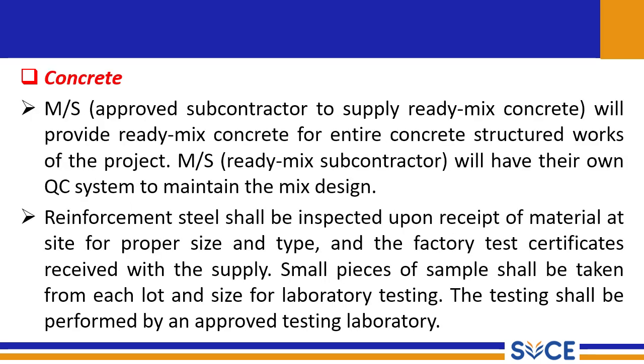Concrete: an approved subcontractor to supply ready-mix concrete will provide ready-mix concrete for the entire concrete structural works of the project, and the subcontractor will have their own QC system to maintain the mix design. Reinforcement steel shall be inspected upon receipt of material at site for proper size and type, and the factory test certificate received with the supply. A small piece of sample shall be taken from each lot and size for laboratory testing, and the testing shall be performed by an approved testing agency.